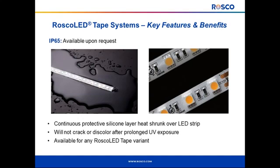I mentioned before that we can offer IP65 variants on any of our tape. This is available upon request. As you can see in the picture on the right, this is actually the IP65 product. So it doesn't incorporate a very heavy, bulky silicone sleeve like many competitor products do. We actually take a continuous piece of silicone and we heat shrink it around the entire length of the LED strip. This really gives a very robust seal, but more importantly, this silicone layer will not crack or discolor after prolonged exposure to UV light. So it's very robust, and we're very comfortable that this will perform extremely well in a broad range of outdoor environments.